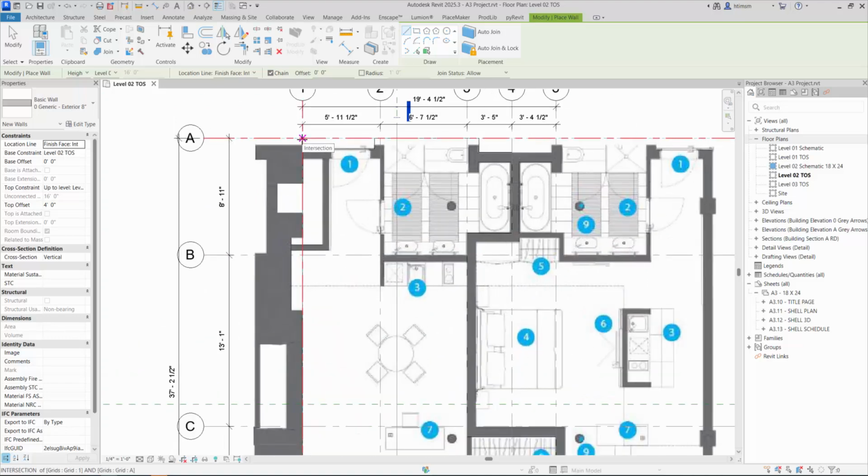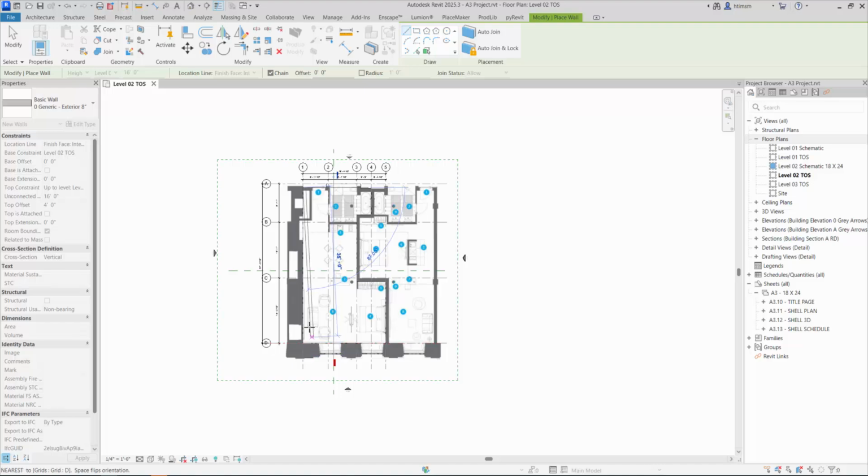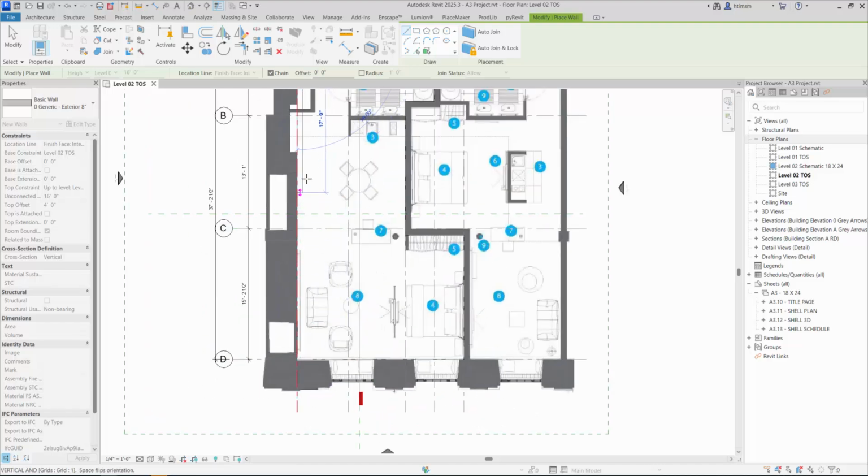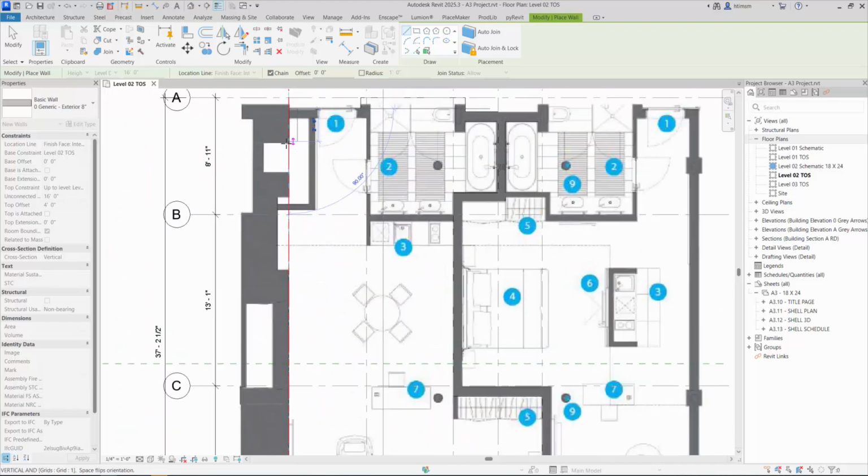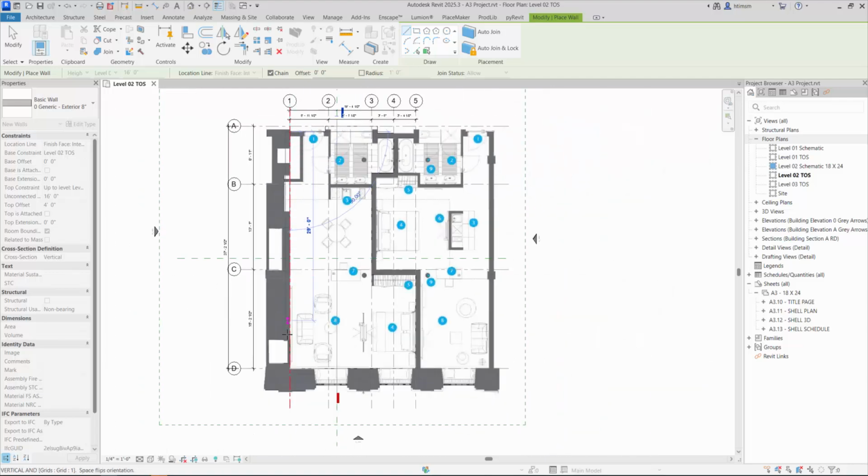things. And so I'm just going to start drawing along the edge of this floor, right? And you can see it's set to interior, but it's flipping. My thing is flipping the wrong way. So I'm just going to hit the space bar. So the wall is actually out there. And again, I'm not worried that this guy is not as thick as that exterior wall. So once I'm done, I'll just go ahead and put this as exterior wall.